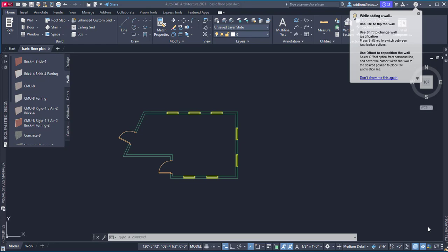So if we have multiple floors, all you really have to do with the initial floor is copy that particular floor. The assumption is that the footprint of that floor plan is the same on the second, at least the exterior walls are the same on the second floor, third floor, fourth floor, and so forth. Again, if you notice on the plan that is before you now, we don't have any interior walls here, because as you move forward and create additional plans for the second, third floor, etc., the interior walls may be different. So we're going to use the exterior walls here.